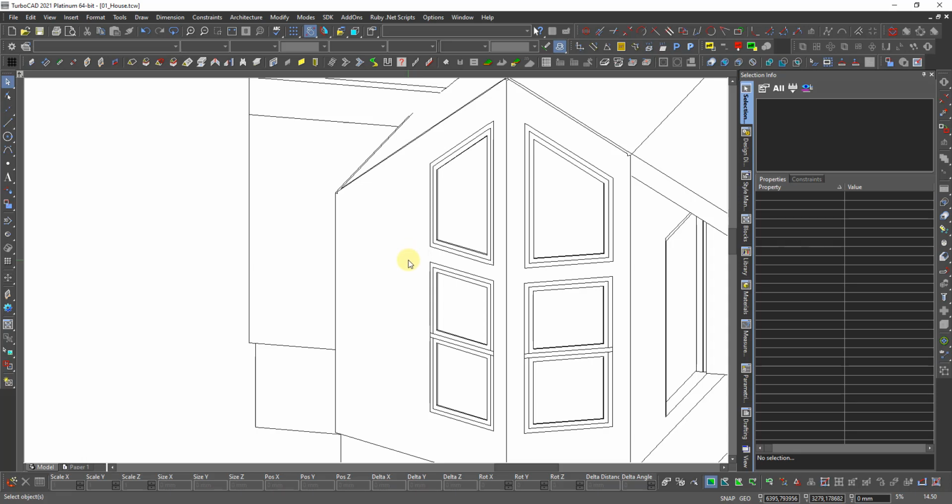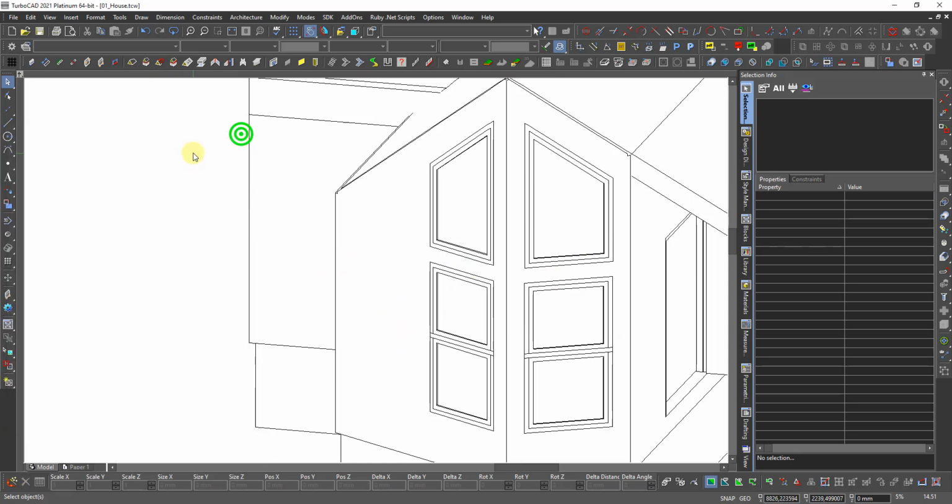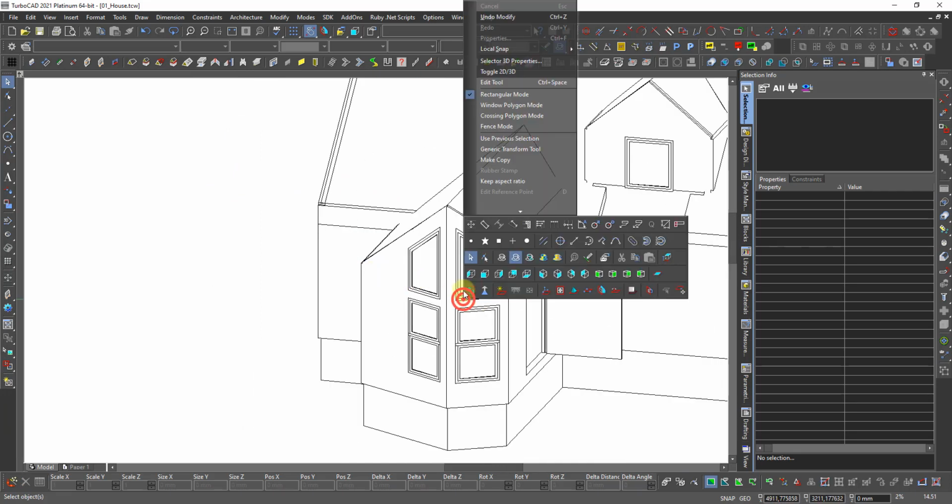It will be 148 plus 13 on the inside, plus 12 outside, plus 23 air gap, plus 19 cladding. 215. Why do I have 65? Because normally today we make 5 centimeter extra insulation on the inside, but it was not like this when they made this. That's the thing. I can show that if I remember it or when I make the style. So I think we stop here.